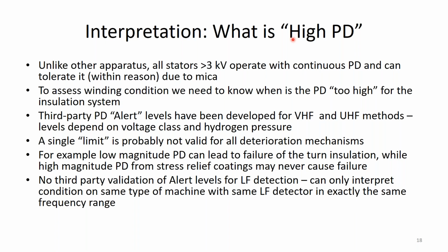We've been able to do the same thing for the most part in interpretation of PD levels. And of course, the purpose here is identifying, if you have 100 machines, which 3 or 4 machines you really need to concentrate your maintenance activity on. And so you can take fewer outages or do less testing of the good machines.